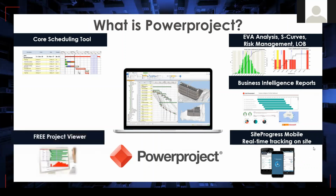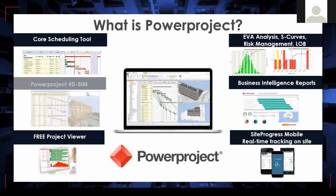It also has a free project viewer where you can send the project information, even if you have the BIM model, so everyone can see it with the project viewer. The sending party doesn't have the right to change any data, so they can only display the information with the project viewer. And also Powerproject has the 4D BIM part. If we have the BIM model, the 3D design of the model, we can combine it with the schedule to optimize it, and we can also have timeline schedules with the baseline schedule. You can have comparison simulations too for progress control.